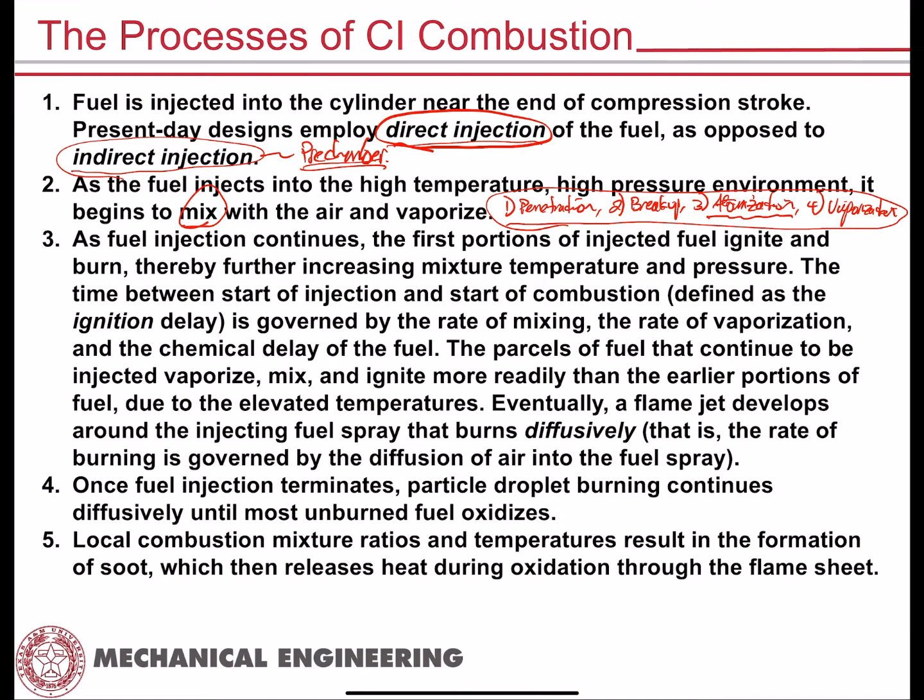But anyway, that time between the start of injection and start of combustion, that's what we call the ignition delay. We've already talked about this. And it is governed by the rate of mixing, the rate of vaporization, and the chemical delay of the fuel. In other words, the ignition delay depends on how quickly the fuel can mix, how quickly the fuel can vaporize, and how quickly the fuel can undergo the chemical ignition process, okay?